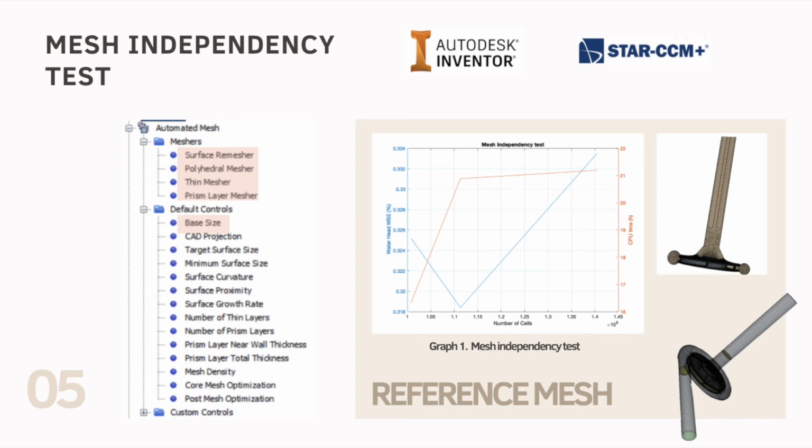After having carried out the design of the pump in Inventor, the result was exported to the STAR CCM+ program in order to simulate the mechanical behavior of the two fluids, water and oil. However, before carrying out any simulation, it is important to first carry out the internal extraction of the volume and then its meshing to guarantee better results when performing analysis on each geometry. For the mesh generation, we used a polyhedral mesh that generates a more stable, precise, and less diffusive mesh, a thin mesh that works for very fine geometries, and a prismatic mesh to improve the precision of the fluid solution.